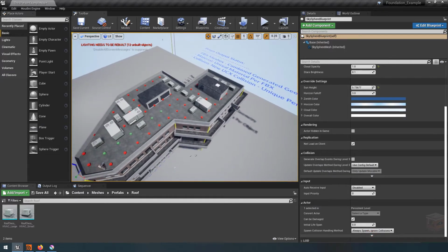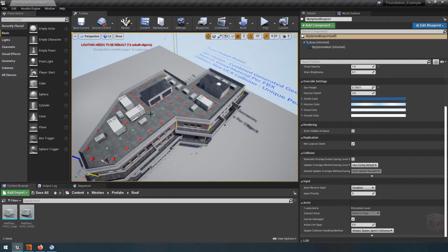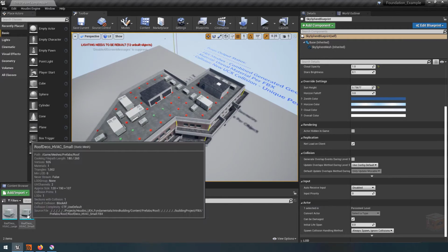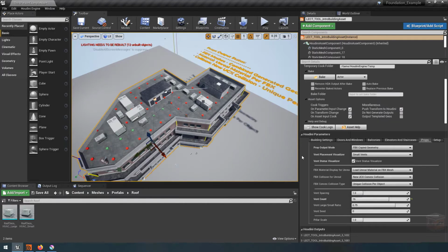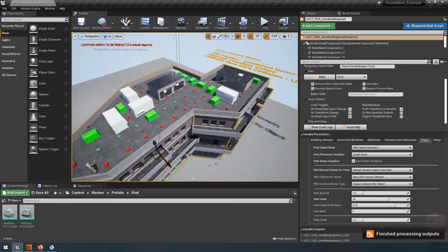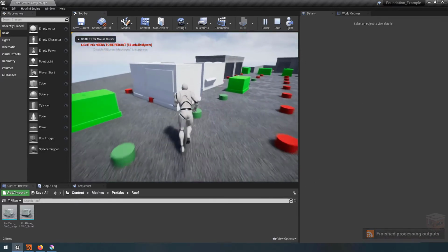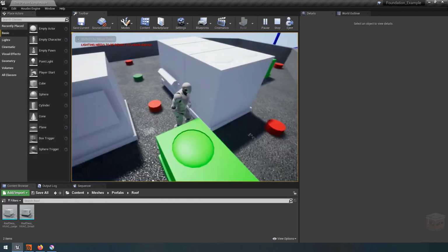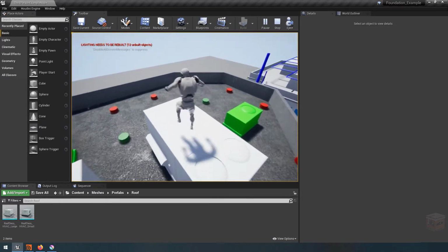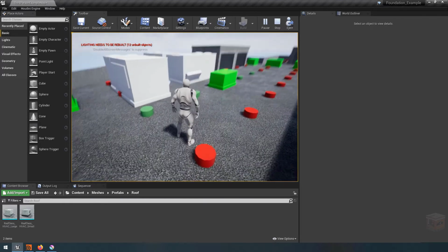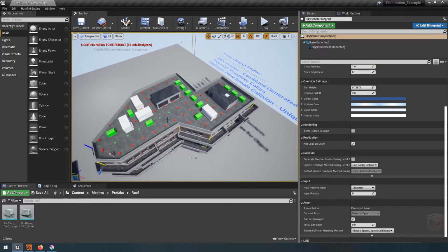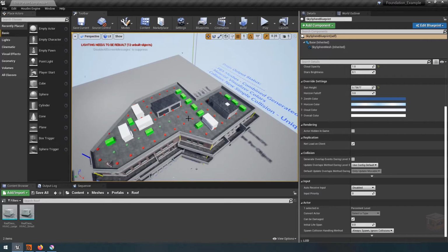And you can see that right now, it looks like nothing has changed. But at this point, this building is no longer placing these meshes. Instead, it is taking the FBX files from my hard drive and it is simply recreating them on the mesh, complete with materials, which I can show you if I disable the materials, and also various types of collision meshes as well. And these will still work. I can still go ahead and play, and I will be able to collide and jump on these objects. And there are various types of collisions that we will cover in these videos. And you can also see that there are a couple of extra visualizers involved, and we will cover this in the upcoming videos as well.